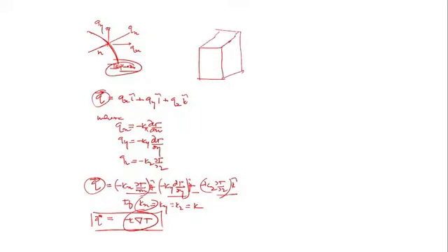Okay beta? Now in this left side wall, if you see, there are three coordinates. This coordinate, and another is this coordinate that is here. So it's x, it's y, let's say it's the z axis. Three axes are there, yes or no? Now, first of all I assume that the left surface is maintained at a constant temperature. Left surface is maintained at a constant temperature, right? And so delta x, this is delta y, and this is delta z.